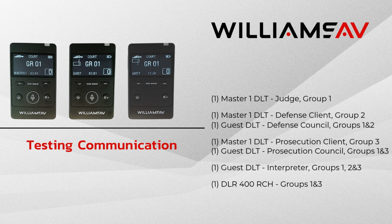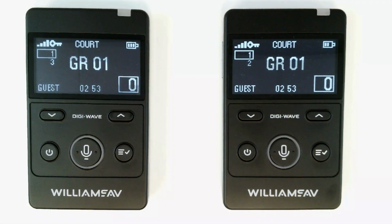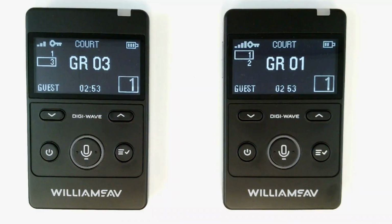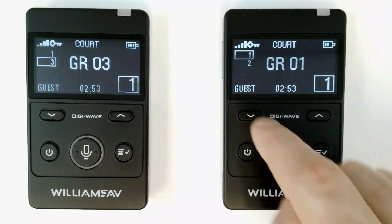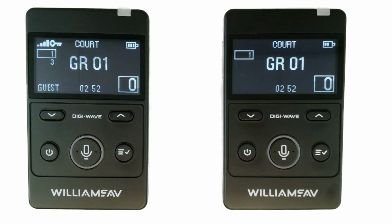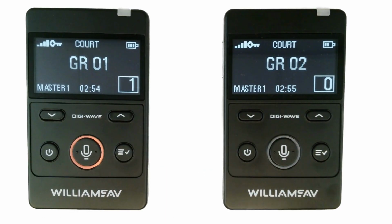With all devices powered on, ensure that all of the devices have signal bars at the top left of the display. The guest or Master 1 should display solid, not blinking, at the bottom left. If guest is blinking, either there isn't a Master 1 powered on or the device is not configured to the correct group. Check your Master 1 transceivers to make sure they're all powered on and configured to the group that you expect.